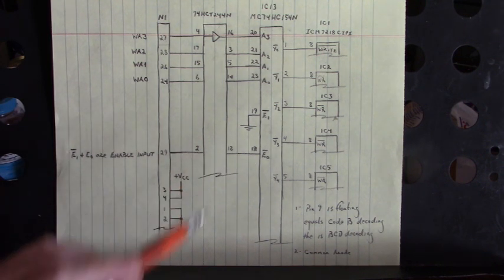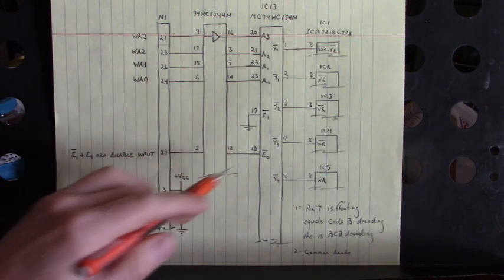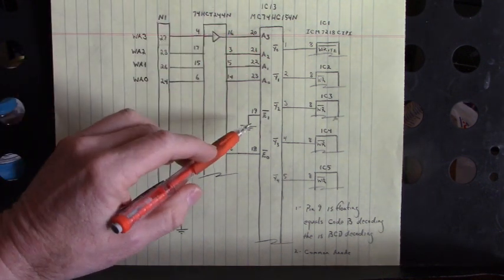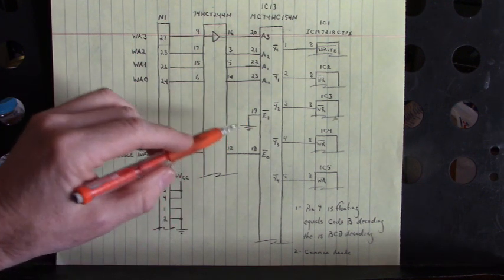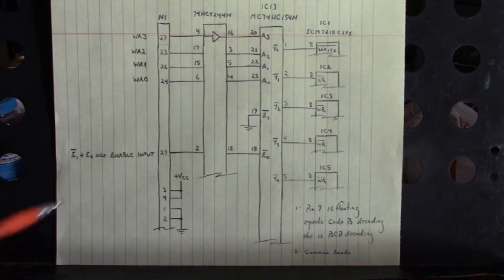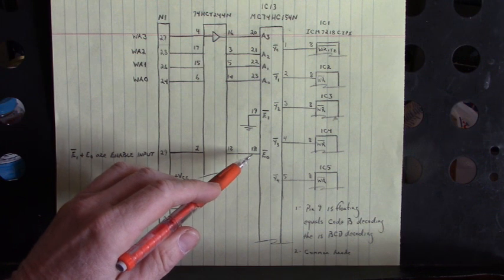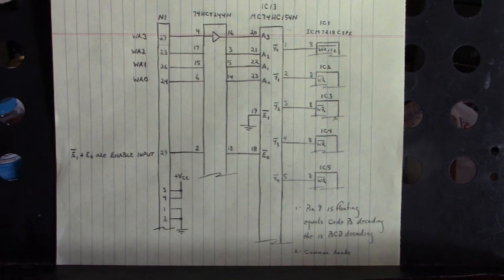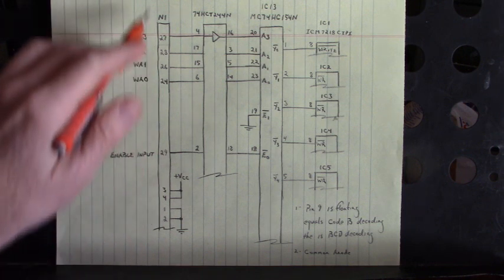We have 2 input enables, and they're not to be confused with the output enables. These are input enables according to the data sheet of this IC. Now input enable 1 on pin 19 is tied to ground, so that's not being used. It's already asserted low. Input enable 0 on 18 is controlled through this buffer IC 74HCT244N on pin 29 of this ribbon cable.